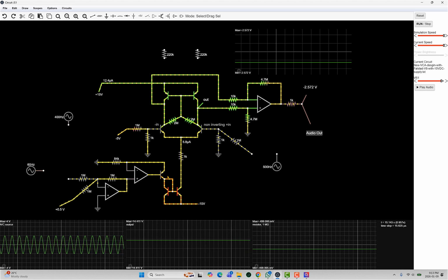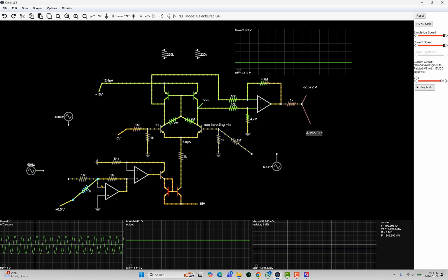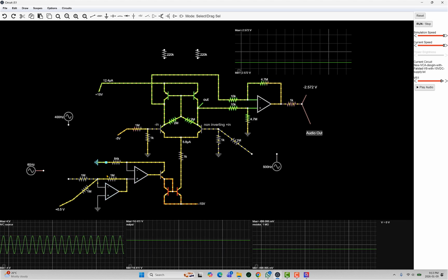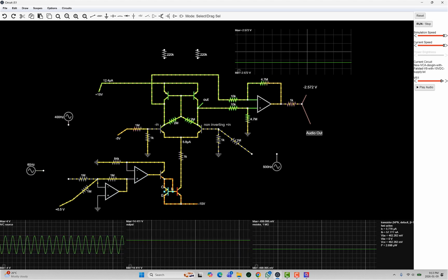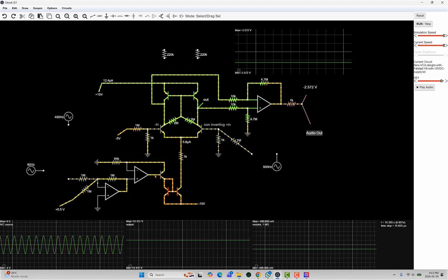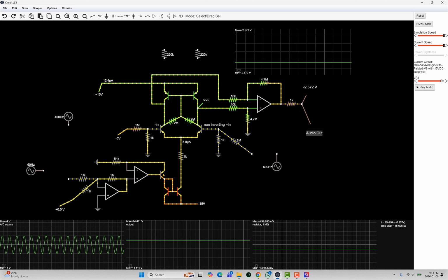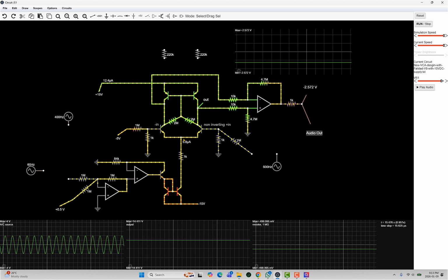And the current I'm measuring is this current here. This resistor sets the current, and then the current is constant through this line here. And this is a mirror circuit, so whatever comes down here is going up as well, right? It's like they're both sides of the same current.